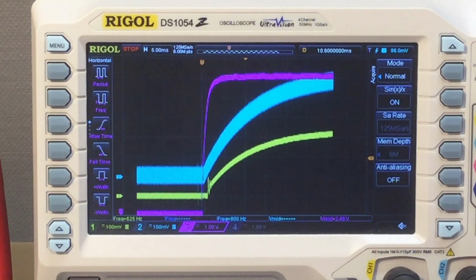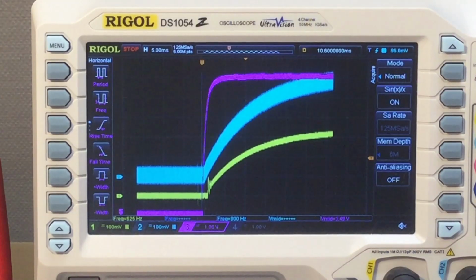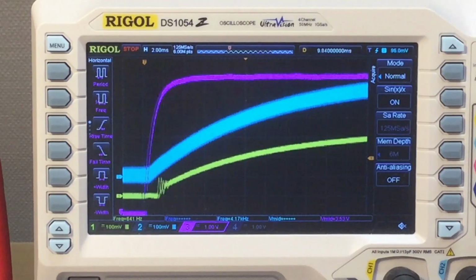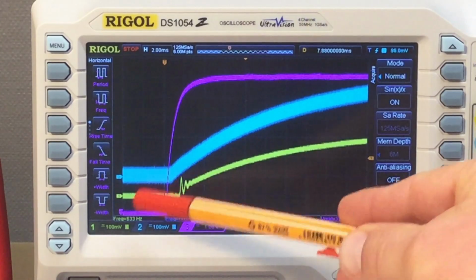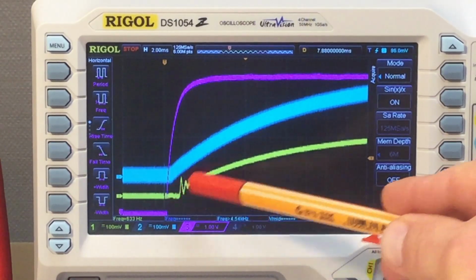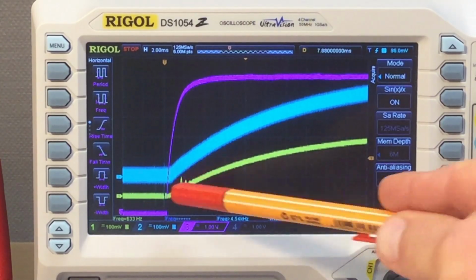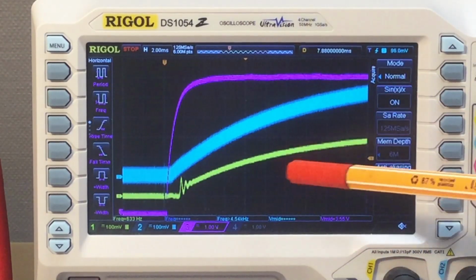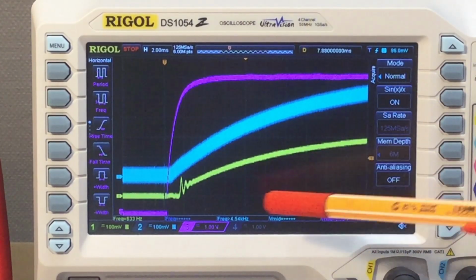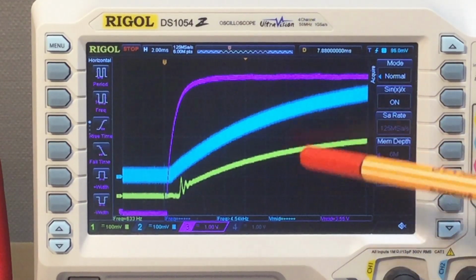Did I capture this in its entirety? Not quite. Doesn't matter, but it doesn't oscillate. I think for that simple circuit, we can ignore that little fluttering here. We could slow down the ramp up even more, but instead I want to see if a 47 nanofarad capacitor would be enough.